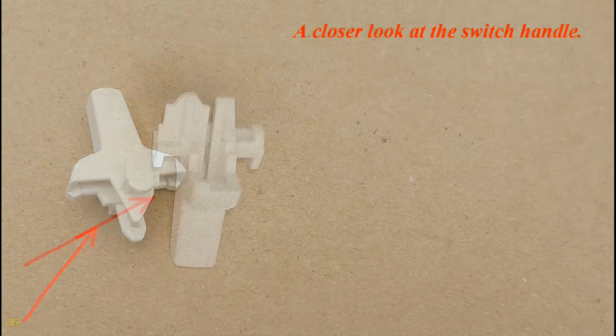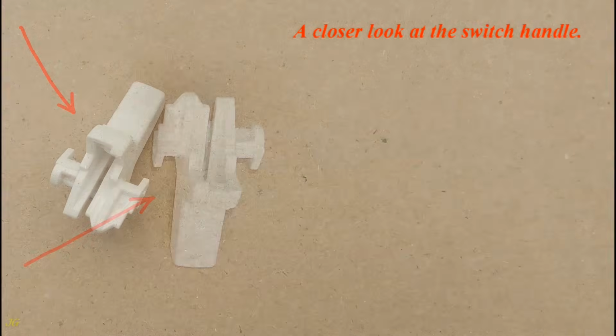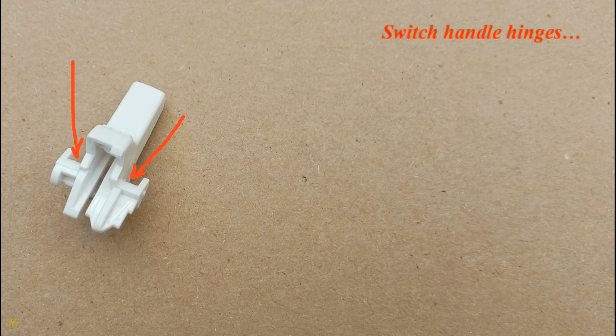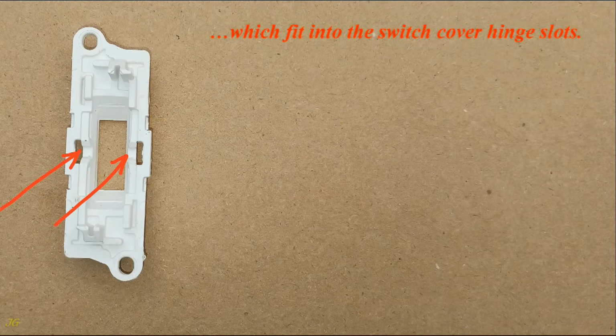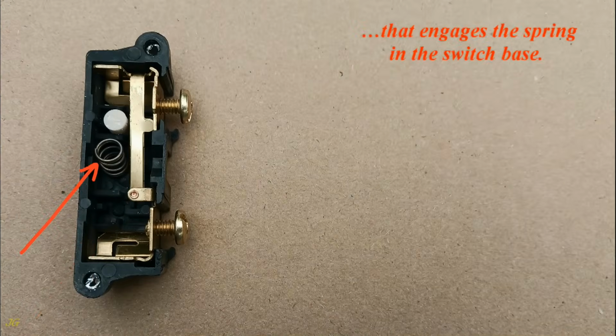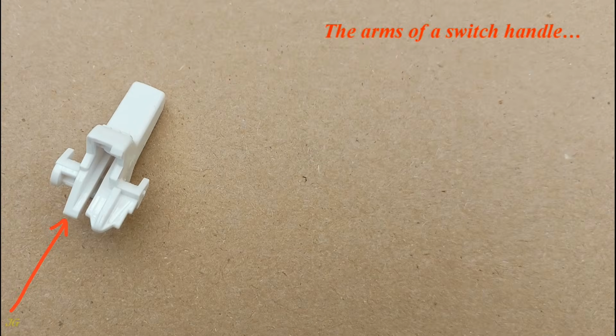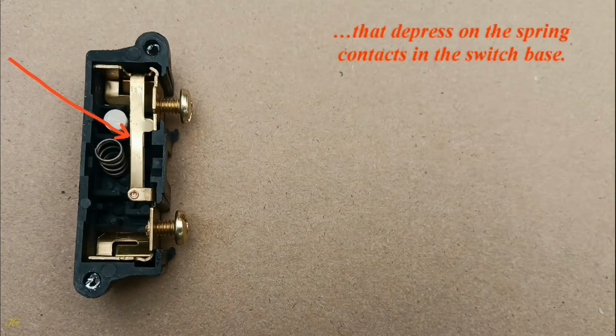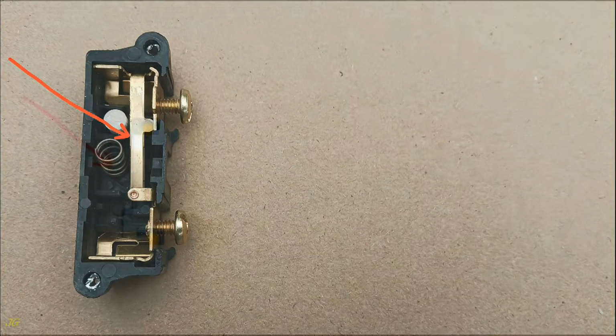A closer look at the switch handle. Switch handle hinges, which fit into the switch cover hinge slots. The switch handle cone that engages the spring in the switch base. The arms of a switch handle that depress on the spring contacts in the switch base.